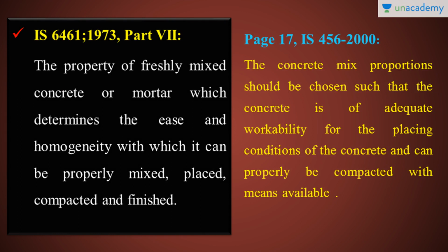First and foremost, from IS 6461 1973 Part 7, this is a very important code book because in this code book almost all the definitions based on concrete technology are provided. Please have a look at this 6461 code book. I think there are 8 parts to it. So let's start with the definition from the Indian Standards itself. It says that workability is the property of freshly mixed concrete or mortar which determines the ease and the homogeneity with which it can be properly mixed, placed, compacted and finished. It's a very straightforward definition.